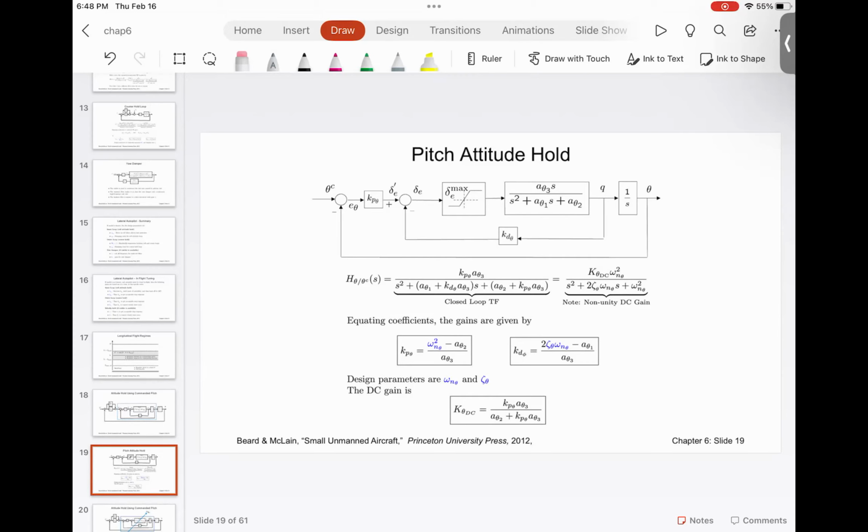There is a physical limit to the control input. So there is something called saturation that makes sure that even if you increase it beyond a certain limit, the control input gets saturated, because that is the physical limitation on the hardware. The pilot, so if the lever can go from here to here, you can't prescribe a control input that asks the pilot to push the lever all the way over here. So there are physical limits. So you will see, even in quadcopter control systems, you will see a saturation function because of the physical limits on the hardware.